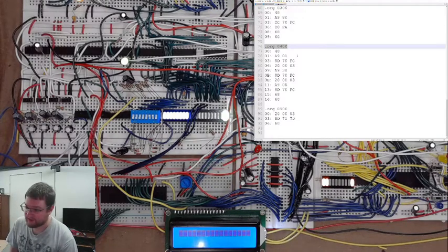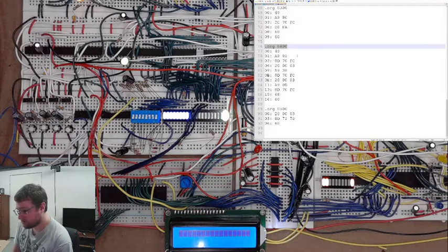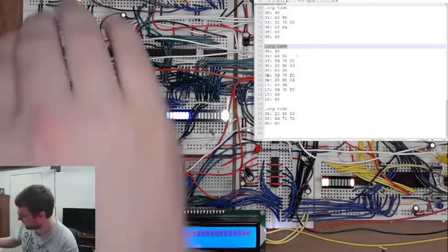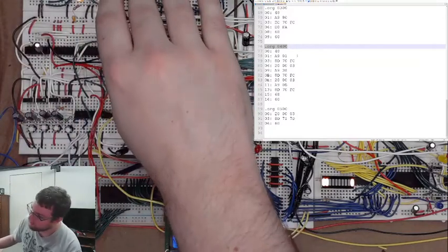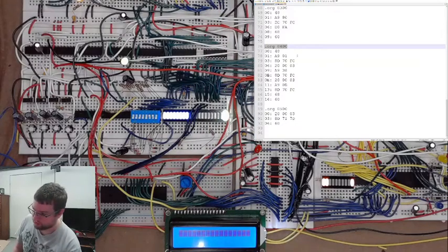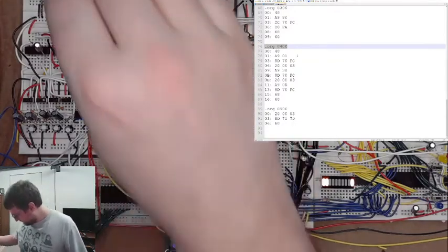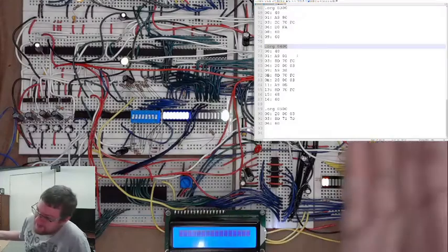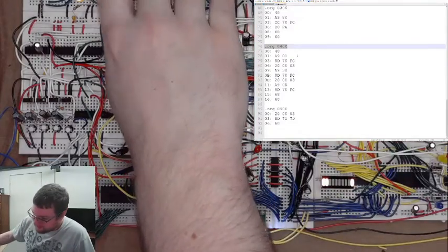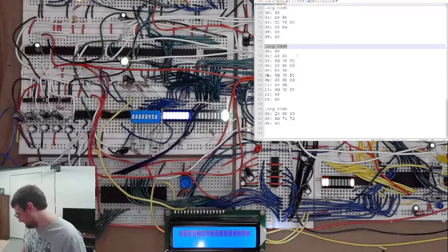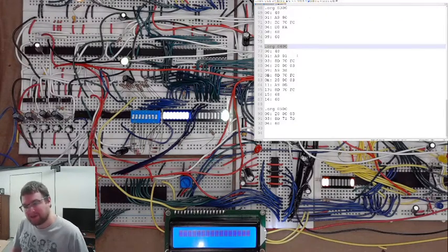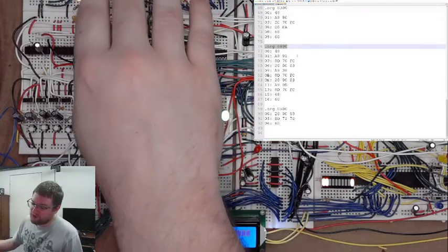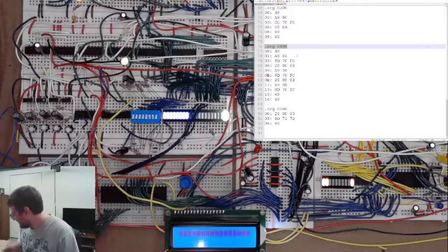So I think that chip just wasn't having enough power available. It needed more. And so we're giving it more. And so hopefully that's going to keep the glitches away. We've given it its own little personal 10 microfarad battery. And that should do the trick. Technically, it probably only needs like 100 nanofarads. But I can't get my capacitors that are 100 nanofarads to span that kind of gap. So it gets a bigger capacitor. A much bigger one. Oh wait, this is only 1 microfarad. So it's not quite as crazy as what I just said.